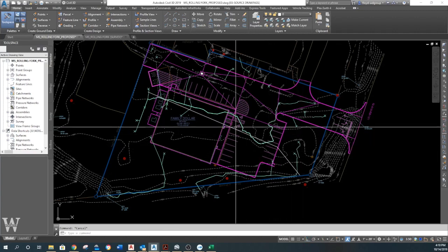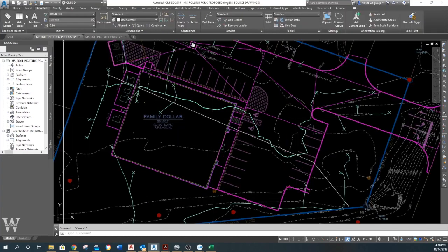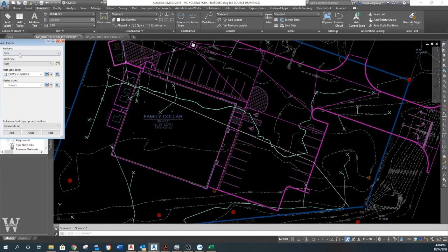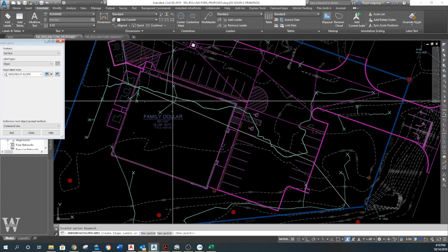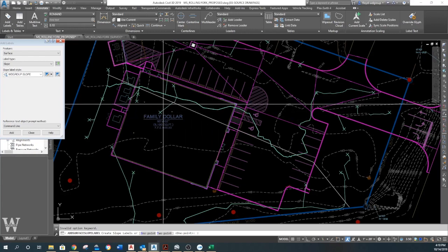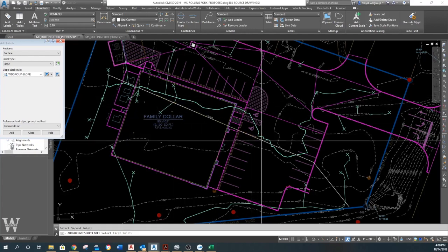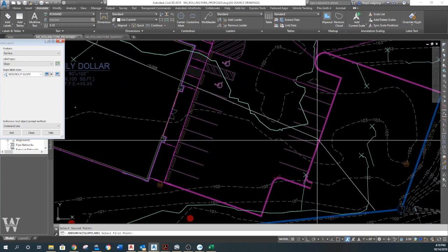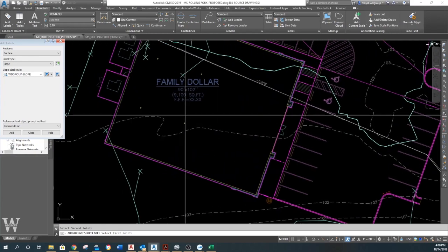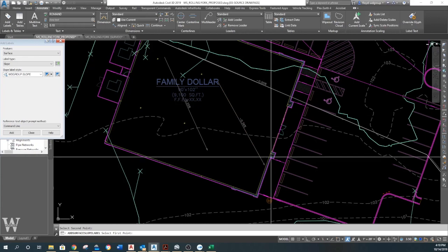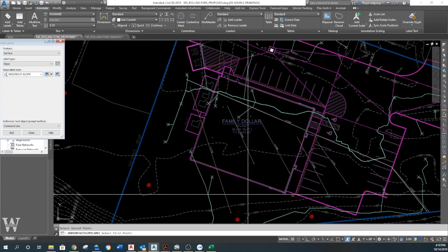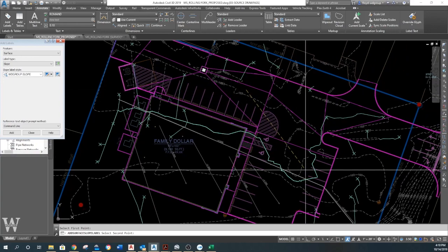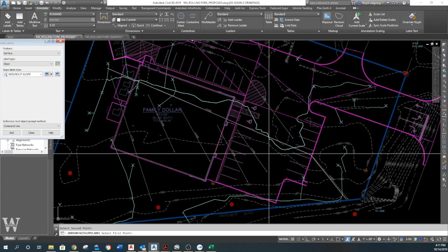Okay? And so I'm going to do a couple of things. I'm going to use my tools here. That's why I have them. Do some slope on this. And let's see. That's pretty flat right there. That's 2.8%. That's 0.25. That's 0.36. 0.99. Okay. So I'm just trying to figure out how I'm going to figure out my time of concentration.